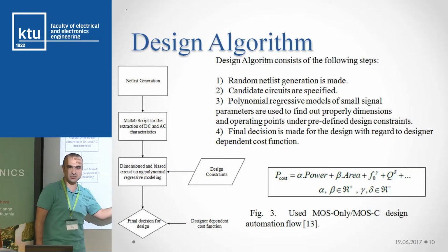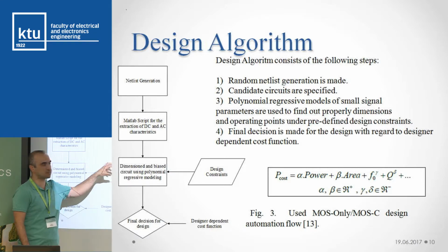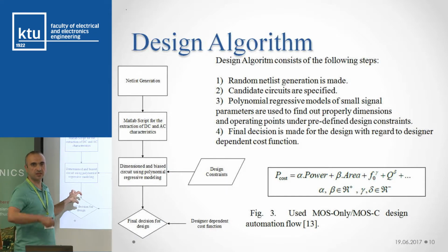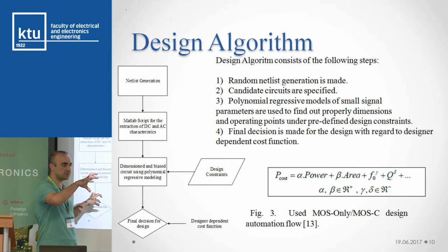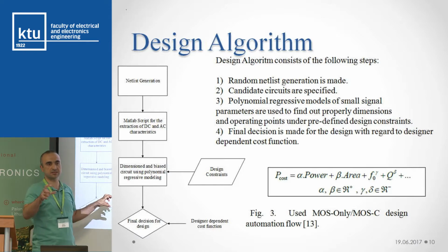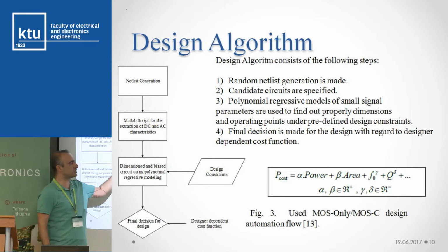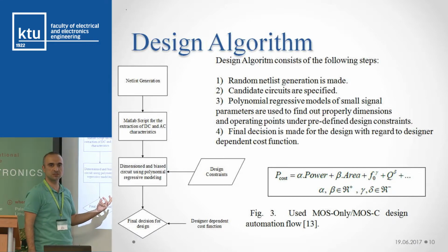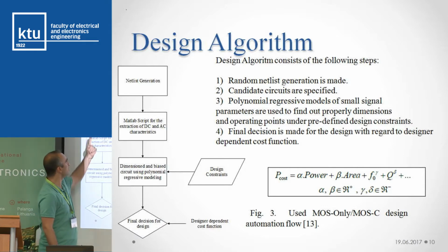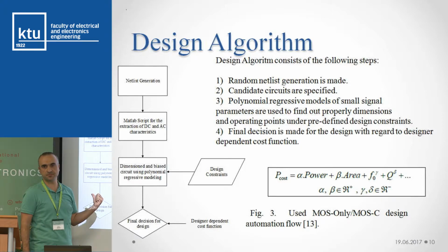If the transfer function gives me a first order filter circuit, then I select this one. It's a candidate. I again rerun the software, and it regenerates another topology which is randomly connected. And if the transfer function gives me another first order filter circuit, I also use this one. It's another candidate. Then I generate the netlist of these candidate circuits.